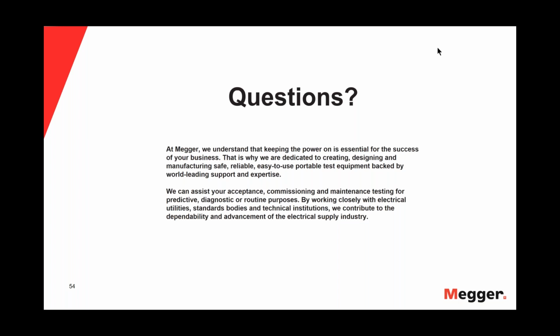So, an old cable, that's why you try to minimize the thump time on cables, okay? And sometimes we actually use thumping when we need to condition the fault, like you have a wet cable. Take that example, okay? You have a wet cable, doesn't flash, so you thump it a few times, you condition it, now it thumps, right? And if you had a cable that has almost a fault, and you thump it a few times, you might fail it because now it's a pinhole, okay? So that can happen, okay?